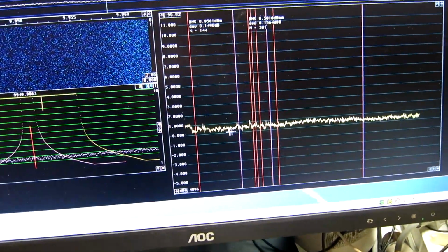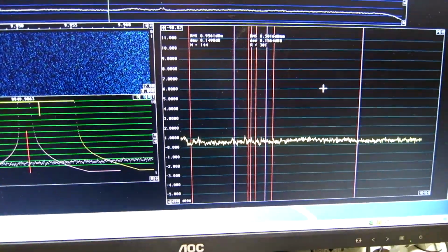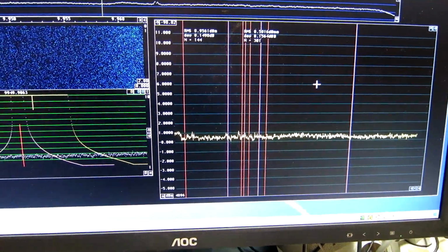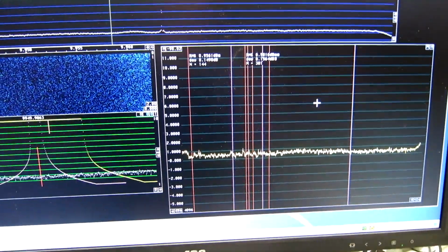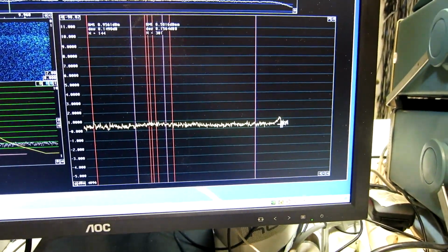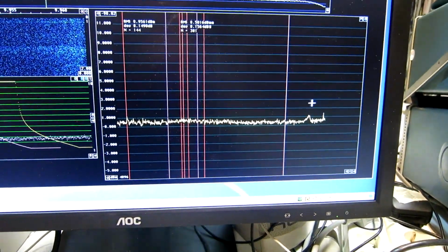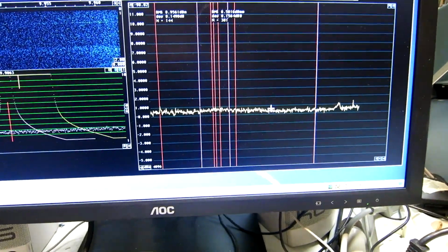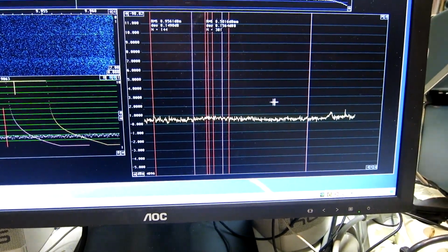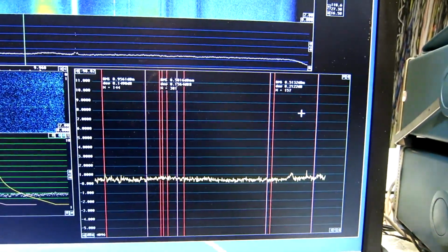But it was a little bit higher at the beginning. Something has become heated or rearranged inside this capacitor. But occasionally there are some noise bursts, but at low levels. So I rate this capacitor at 0.5.